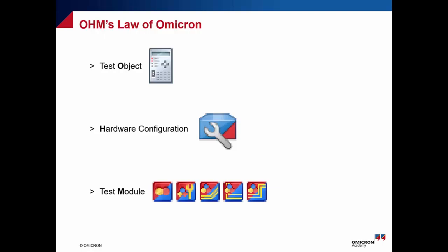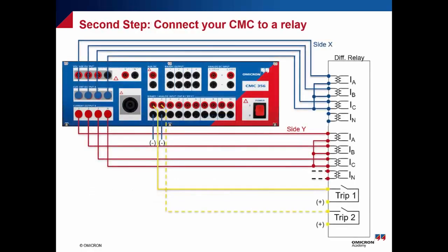How do we need to connect? As we see right now, for transformer differential, for sure, if we have a two winding, we have to connect primary and secondary as well. We can use two different commands, two binary inputs, one for high side, one for low side. In most applications we use one general trip instead of two. We will use only one. We have here a positive and negative for the binary input. We will talk about that later, what it means and why we need it.